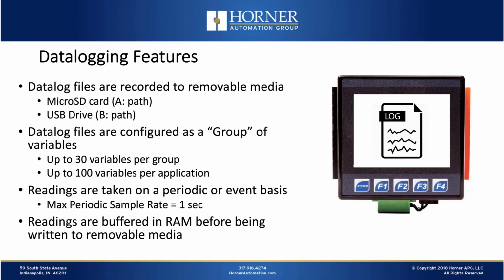Now, readings are taken how often? Well, they're taken either on a periodic, time basis, every second, every minute, every hour, whatever makes sense in the application, or on an event basis. Whenever a particular condition occurs, it can be detected by the logic, a bit can be turned on, and a reading can be taken.